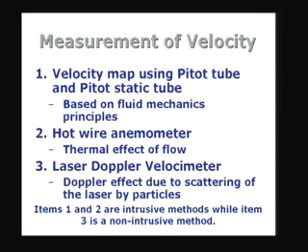So, the pressure reduces, and the temperature is going to increase because we are putting a certain amount of heat into it by sending a current. The temperature is going to increase as the pressure decreases. In the case of the Pirani gauge, we are looking at the pressure as a function of the temperature of the element, whereas here in the case of a thermal